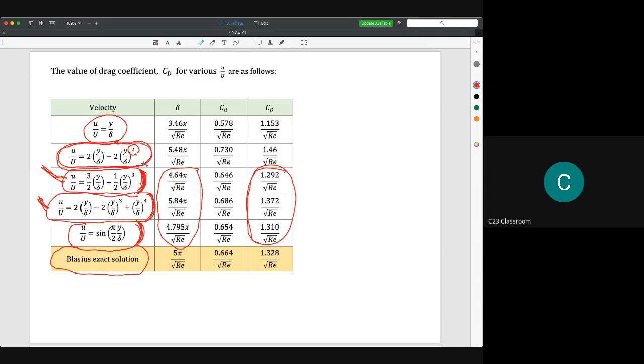Means that if you assume that your boundary layer has a velocity profile of quadratic, by the power of 2, so mean this is the velocity profile. You cannot write another profile because it does not fulfill the momentum equation. Means the Navier-Stokes equation. Okay.